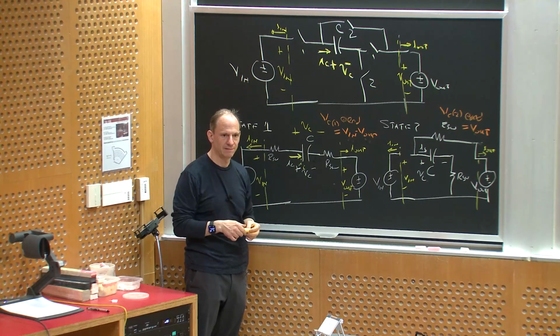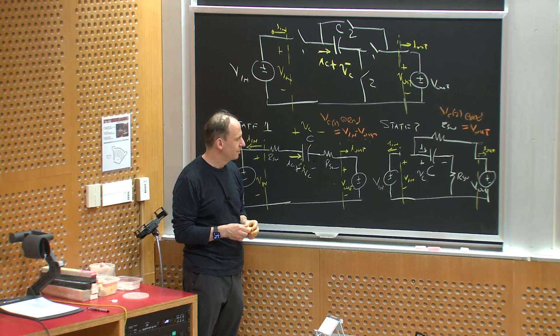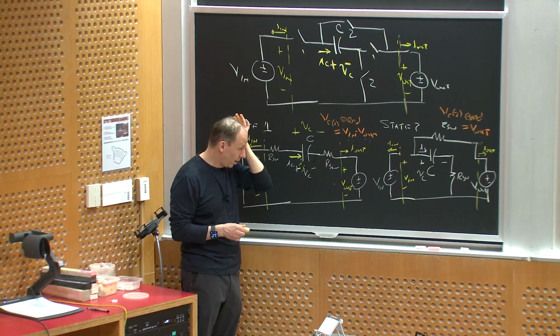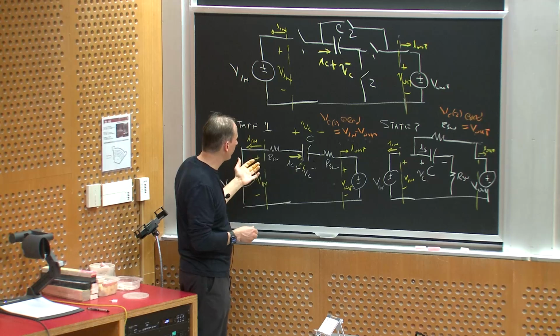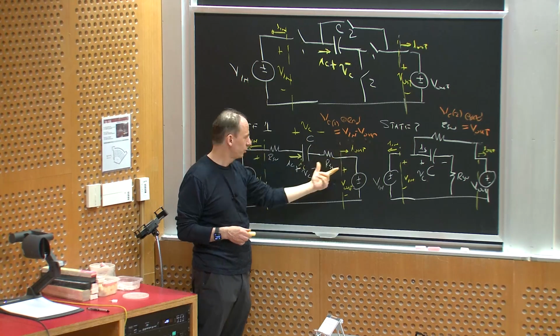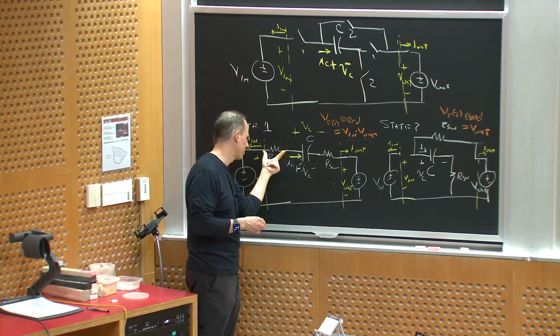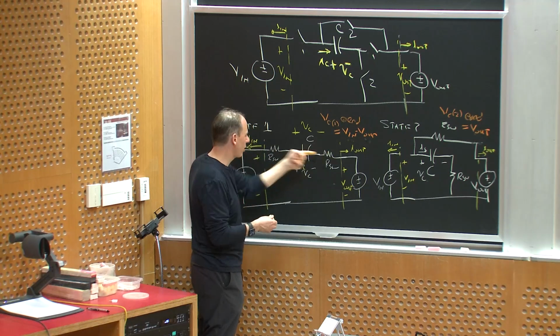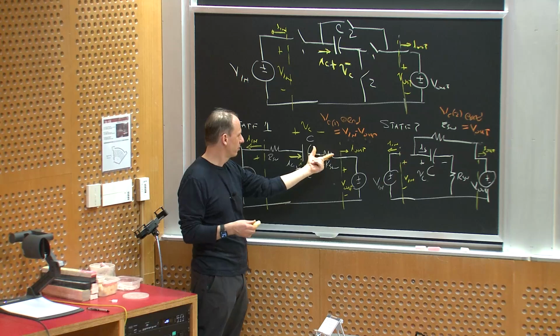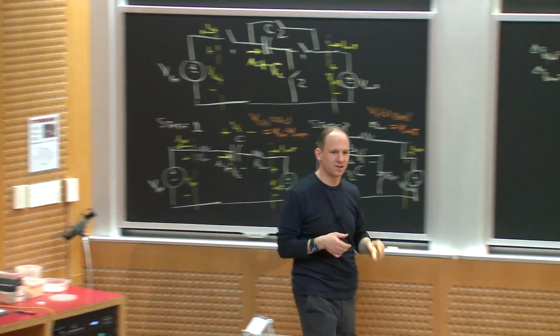But wouldn't the on-state and off-state voltages change? Wouldn't there be potential differences across the resistors? Well, if I've assumed that the capacitor is fully charged, the voltage across this resistor went to 0 by the end, right? The only assumption I've made is that this capacitor charges. Once the capacitor current goes to 0, these voltage drops go to 0. We'll relax that assumption shortly.